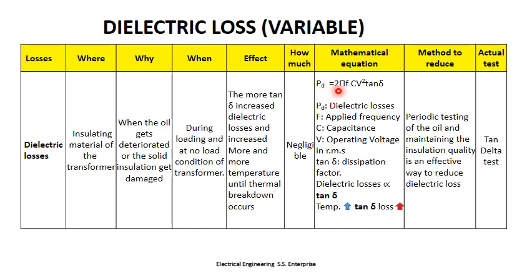A dielectric loss is equal to 2πfCV² tan δ, where f is the applied frequency, C is the capacitance in farad, V is the operating voltage in RMS, and tan δ is the dissipation factor. Dielectric losses are proportional to tan delta. As the temperature increases, tan delta and the losses increase.